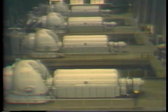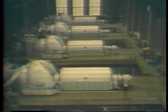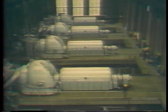A watt-hour is a lot more energy than a foot-pound, but even a watt-hour is too small a unit in many cases. When large amounts of electrical energy are involved, it's common to use units of kilowatt-hours. A kilowatt-hour equals 1,000 watt-hours. In other discussions of energy, BTUs may be used. Now, BTU is larger than a foot-pound, but smaller than a watt-hour. Now, in this segment, we'll show you the conversion factors for converting foot-pounds to kilowatt-hours. And then we'll go on to cover power, the rate at which work is done or energy is used.